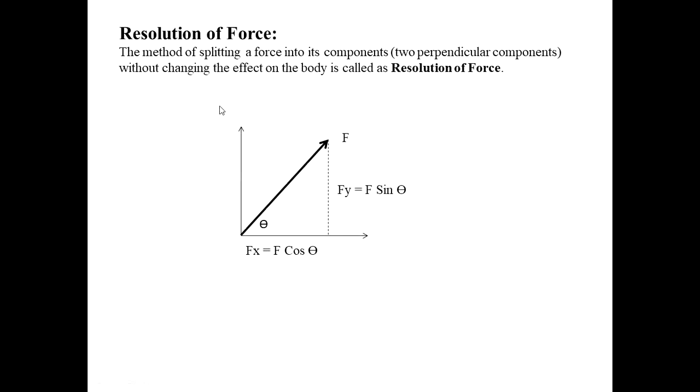Next, resolution of forces. The method of splitting a force into its components, that is two perpendicular components, without changing the effect on the body is called resolution of force. Resolution of force is exactly the opposite of composition of forces. In composition of forces, we convert two perpendicular components into a single force, and in resolution, we split a single force into two perpendicular components.